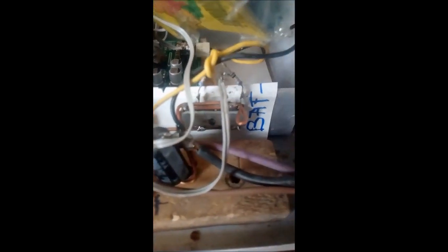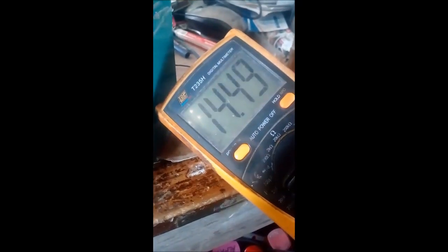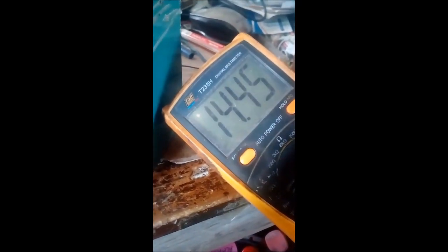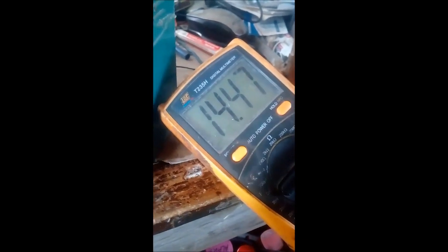Okay, right, and that's the power module. Battery negative there, and the solar negative side switch there. Okay, it's charging. Okay, right, and it's regulating at 14.48, okay, 14.5 volts. Right, just a bit.